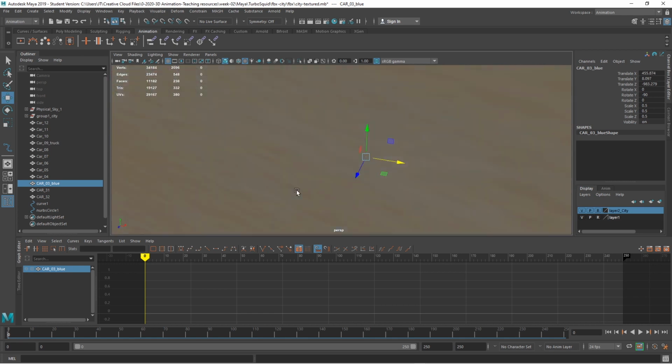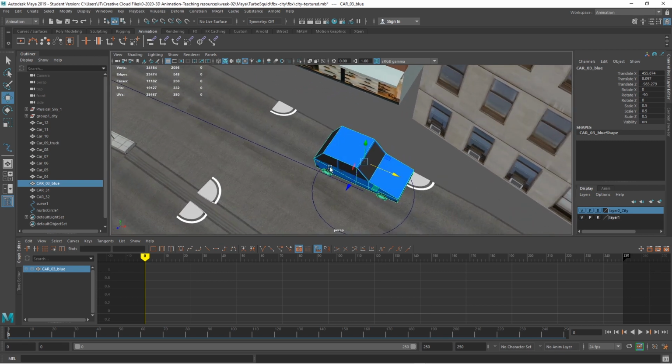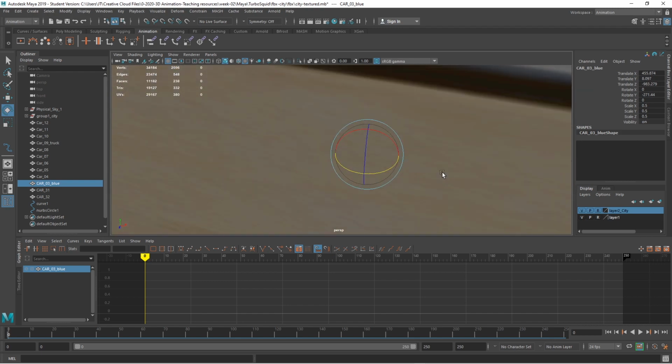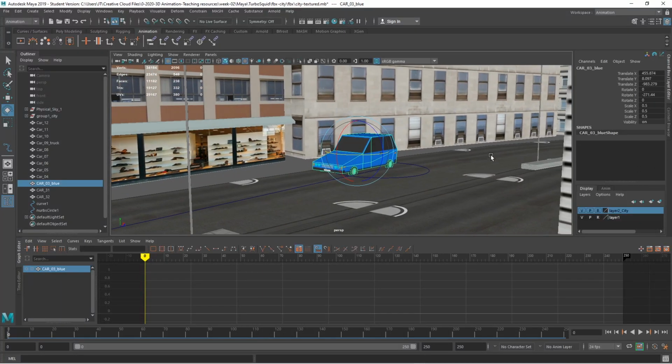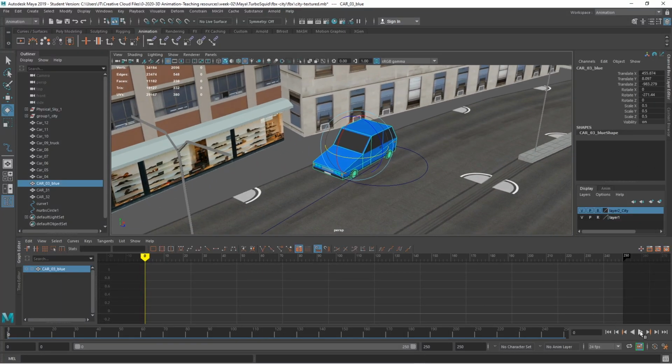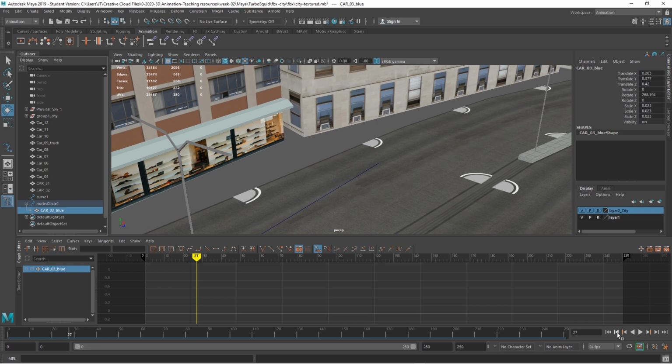Now this really only works because it's a straight line, so if you're doing curves, well, it will work with a single car. If you're doing this with multiple cars, like I'm going to demonstrate in a moment, you will probably have to stick to using just straight lines. So now that's in position where that circle starts, I want that car to move with the circle. So if you've got a 3-buttoned mouse, you can middle click this and drag that into the Nurbs Circle, and that becomes a child and the Nurbs Circle is the parent. So now I can press play and that will move with that circle itself.